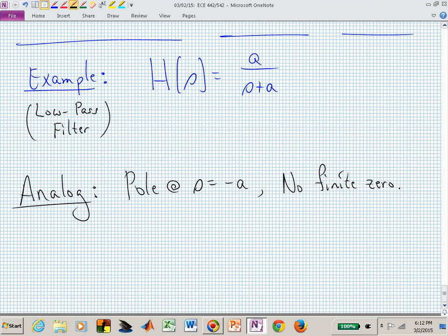Contrast that in a little bit, we'll need to worry about infinite zeros. Are there any zeros at infinity? Meaning, are there big values of S that cause H to vanish, and how many of those are there? That hinges on the order of your denominator. You have a first order denominator, so the denominator is 1 order bigger than the numerator. You have 1 zero at infinity. You can let S get big, and you'll get H of S going to 0. You have 1 zero at infinity.